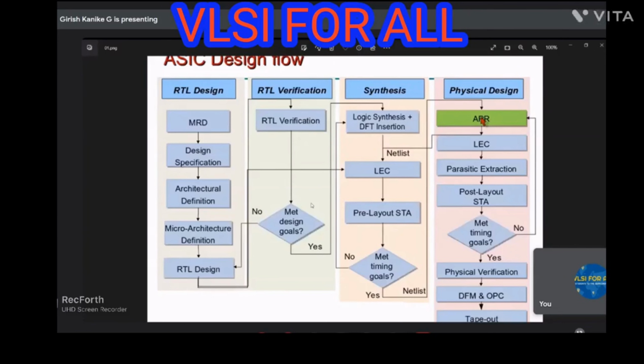If you are giving 1 1, you need to get the output 1. If you are giving a different input, 1 0 gives 0, 0 1 gives 0, 0 0 gives 0. That's the AND gate. So that logic will be checked in the AND gate. So everywhere, the gate level logic will be checked in the logical LEC.